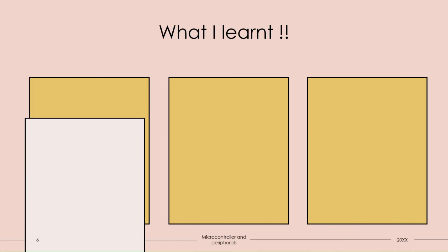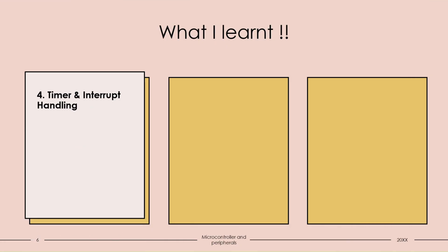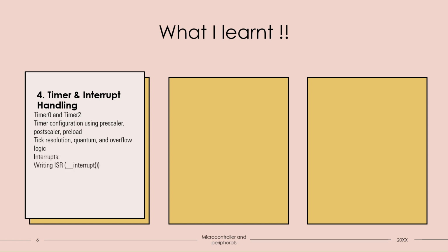Next, we learned timer and interrupt handling: Timer0 and Timer2, timer configuration with prescaler, postscaler and preload, tick resolution, quantum and overflow logic, and interrupts. In interrupts, we used the ISR with flags like TMR2IF for interrupt control, and enabling global and peripheral interrupts like GIE and PIE.